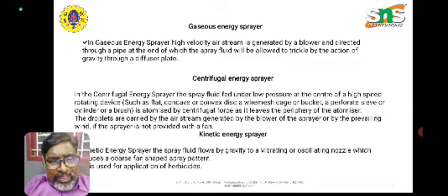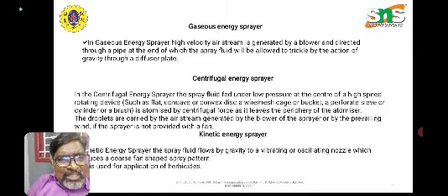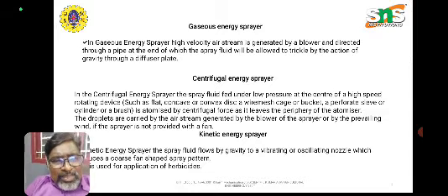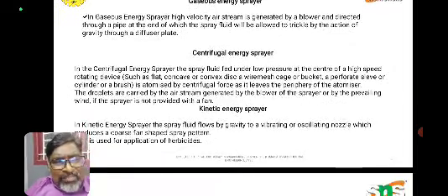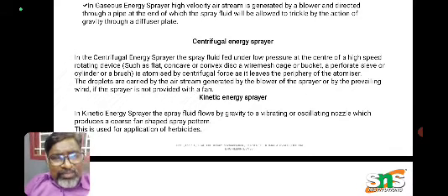The fluid is atomized with centrifugal force. As it leaves the periphery of the atomizer, the droplets are carried by the air stream generated by the blower of the sprayer or by the prevailing wind, in cases where no fan is fitted.